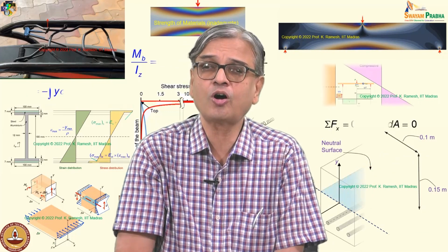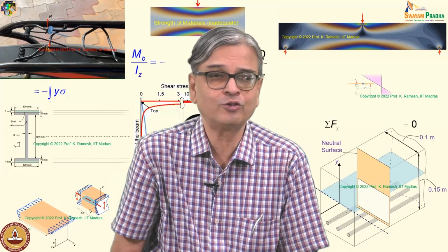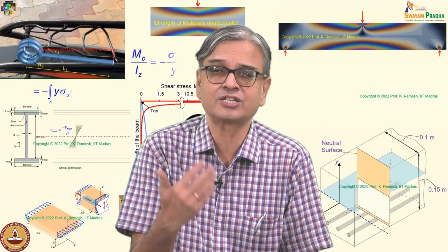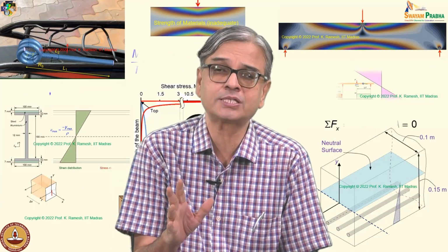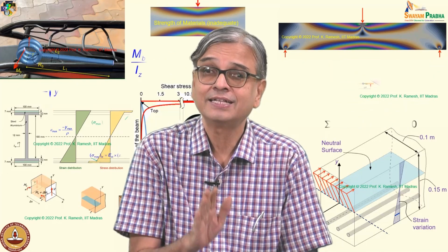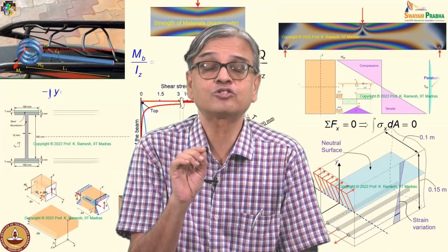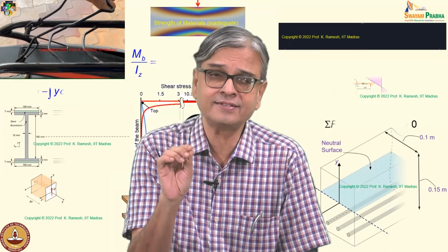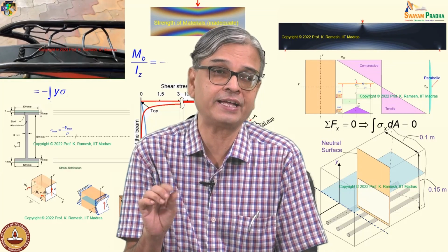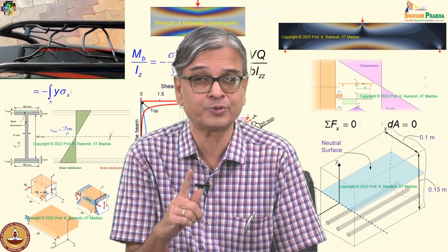And we have looked at composite sections. In one case, the symmetry was not affected, so I do not have to find the neutral surface; I could easily start from that. The important concept was that strain variation is continuous, while there can be discontinuities in stress variations. I also noted that even within a thin section, because it is transmitting bending, the stress varies linearly, in contrast to what you saw in hoop.